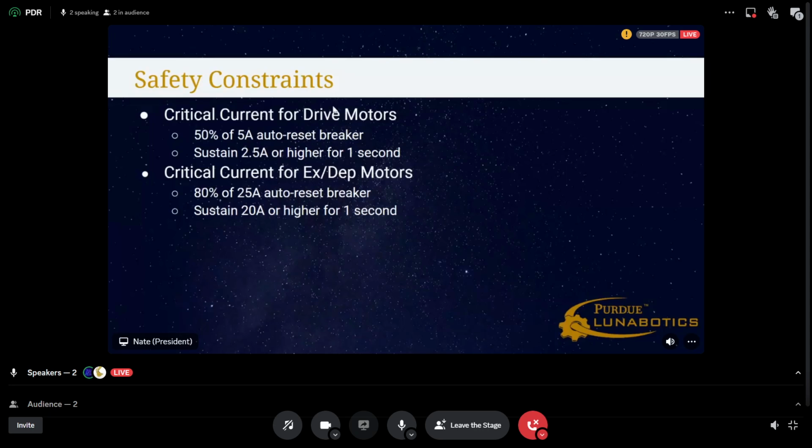There are a few ways to address this. A few members were looking into it, but you can add a Kalman filter at the output of our odometry. Odometry is basically estimation of our current position, relative, differential. You stick the Kalman filter at the output, and its output can be upsampled a lot, so you can run it at a much higher speed. Right now it's around 10 hertz, and we would want it above 20, because you're rate limited by how fast your position output is. You can't have your control running faster than your sensor input.